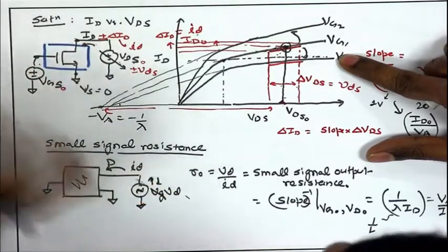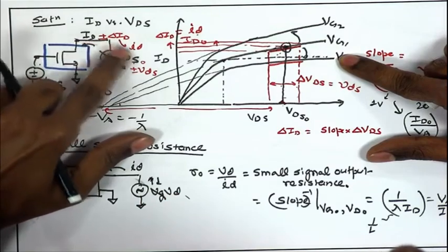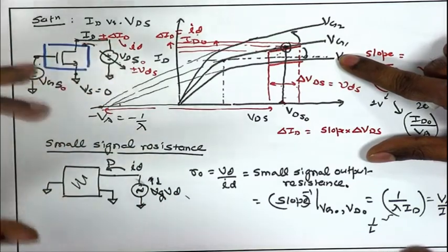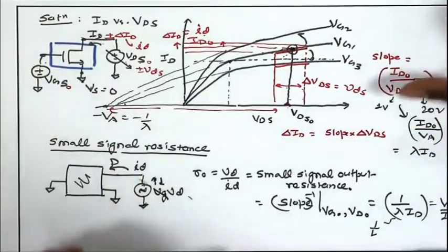The drain current depends more strongly on the gate to source voltage, and not so much on the third terminal, not so much on the drain voltage. That makes a perfect transistor, which is required for analog operation.